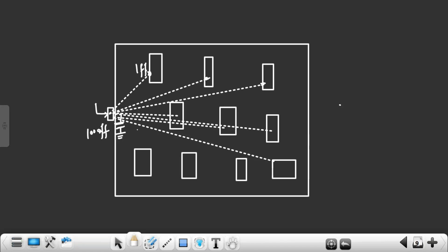Now, if I tell the clock is becoming logic 1, this is the ideal thing. But really, the clock will not become logic 1 like this. It will take some time to become logic 1. It will take some time to become logic 0. Why is this transition there? Because this capacitor should be fully charged. Then only it is called what? Logic 1. This capacitor is fully discharged. Then only it is called what? Logic 0. If this capacitance load is very huge, then it will take more time to charge.